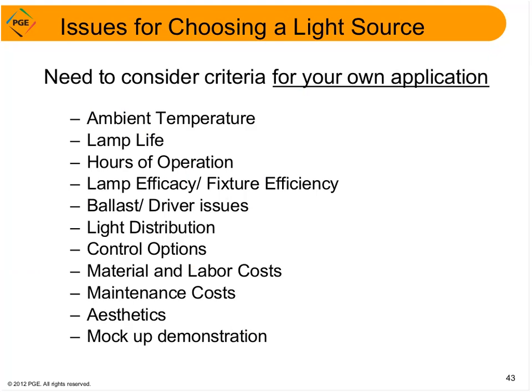So ambient temperature can certainly be a factor. Lamp life, we talked about that, as well as hours of operation. Light distribution, very important. Material and labor costs, certainly the material costs are going to be higher for LED. Labor costs probably going to be about the same. Maintenance cost is going to be an advantage for LED. Aesthetics is very subjective.